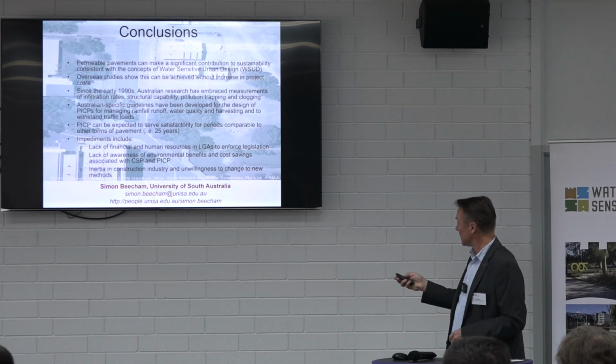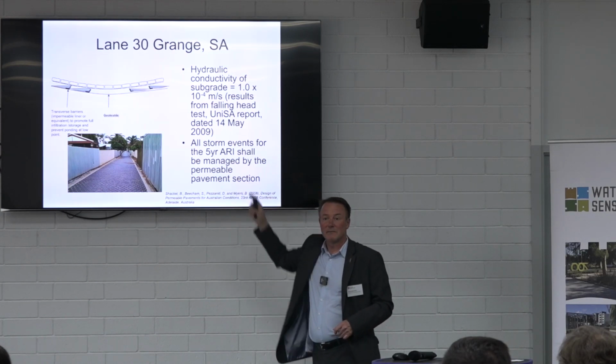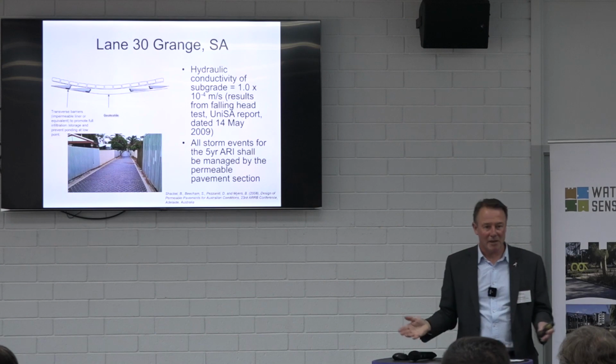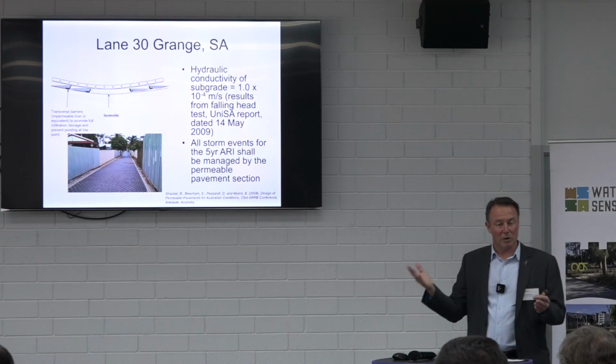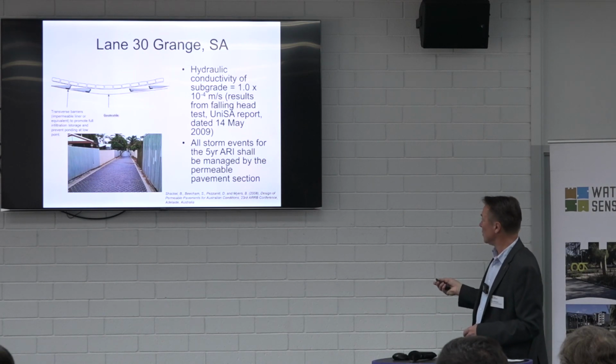Notice though, just to go back a step, a 5-year ARI is not untypical. You might go to a 10, you might even go to a 20, but you'd never go to a 100-year, which is what that Chicago stadium, White Sox Stadium, was.